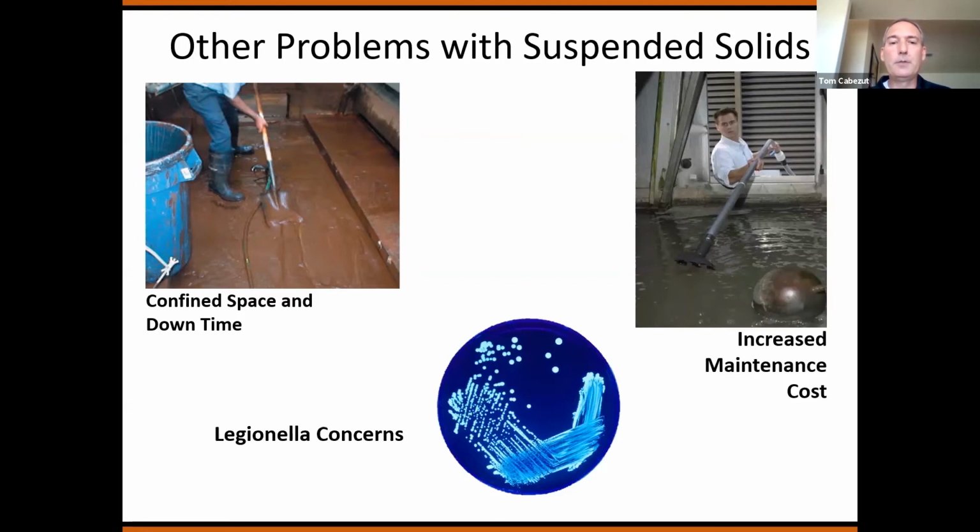And Legionella concerns, the more dirt you allow in your basin to stay stagnant, and if the water treatment can't get to it or the biocides, then you have the concerns of bacterial and biological growth. There was an outbreak at Disneyland that some of you may be aware of. They kept it pretty quiet, but there were a couple people that contracted Legionella over a contaminated tower, and obviously lawsuits are going to ensue. So it's important to maintain the basins as much as you can.